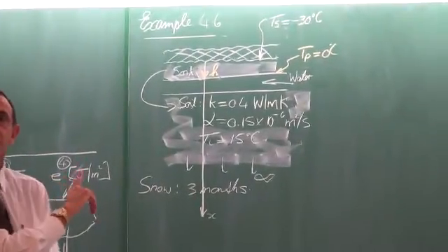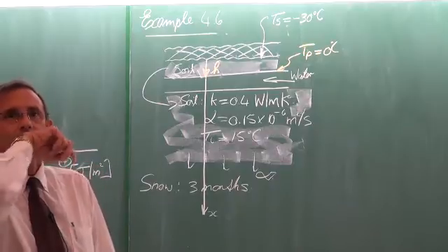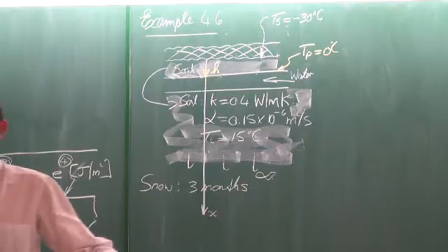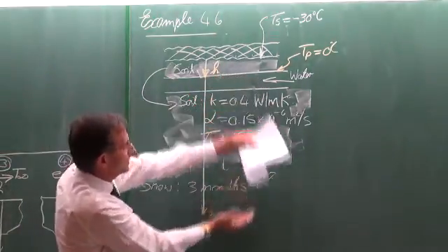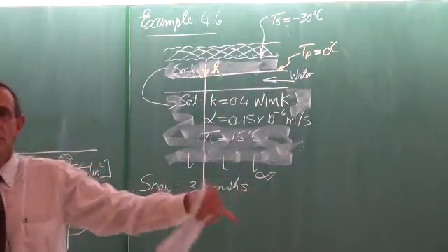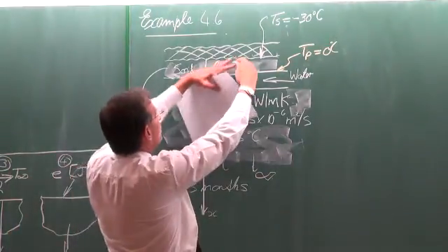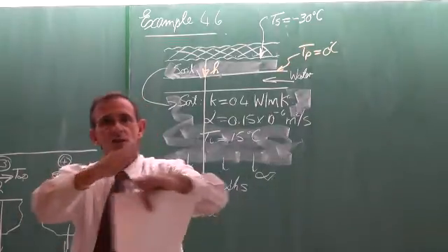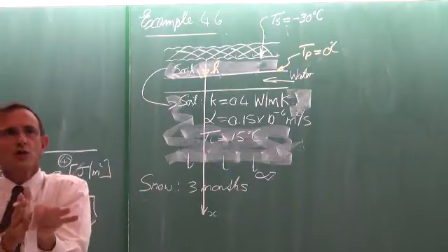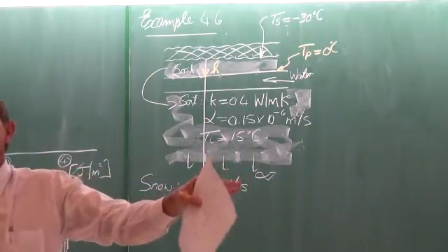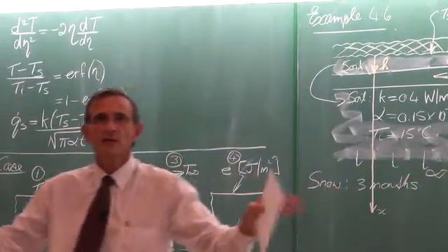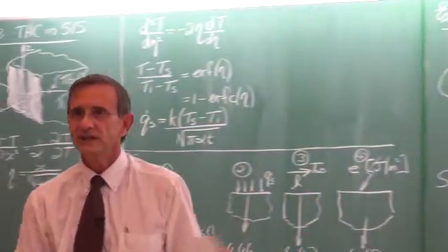Elsemarie, what did I miss? So the Ti, that's the initial soil temperature. Ti is the initial soil temperature, and it would be the soil temperature up to, well, not the middle of the earth, but yes, for a very, very long time, and that would have been the temperature just before it started snowing. It's not perfect, but in general, that is the temperature of the semi-infinite solid, and that cannot change. Always remember, the temperature of the semi-infinite solid remains a constant. It can't change.